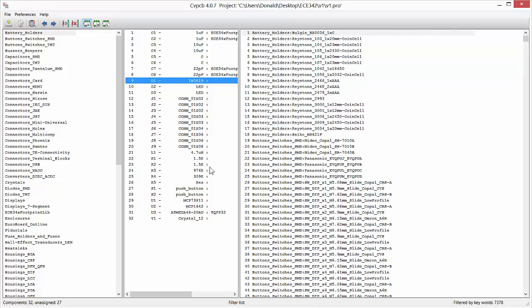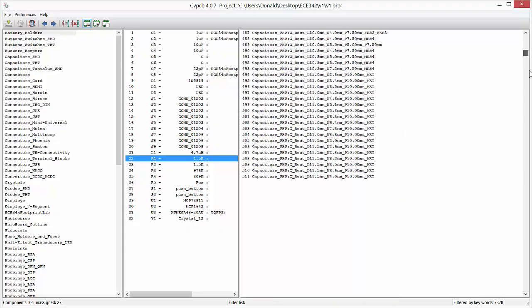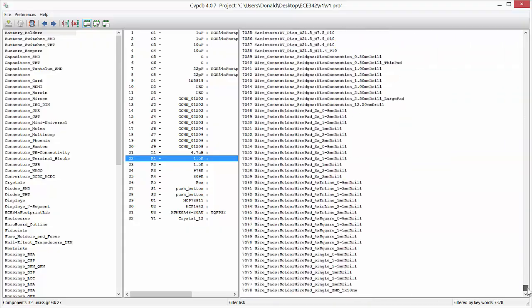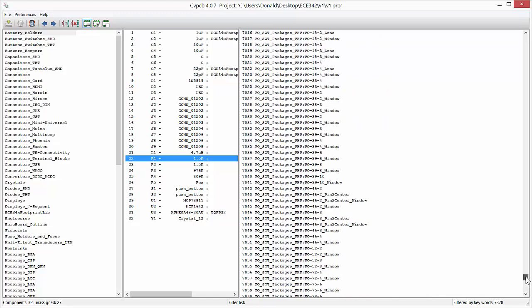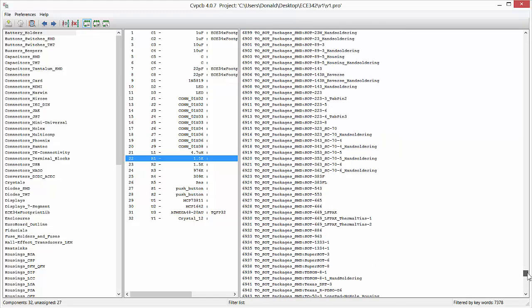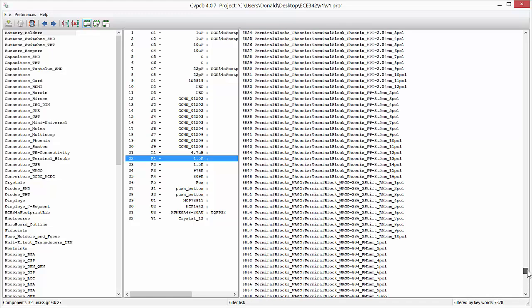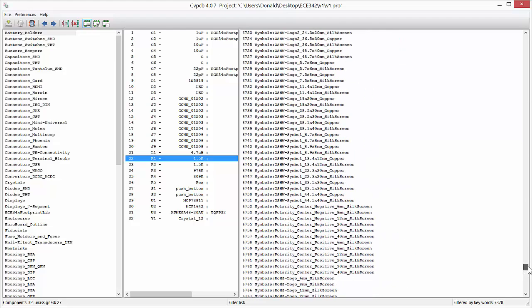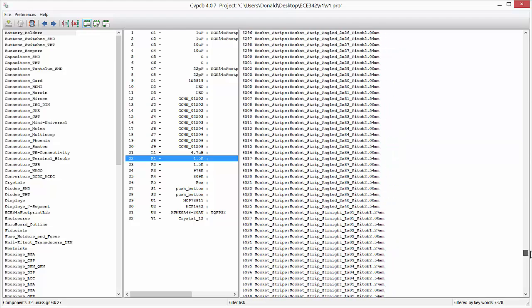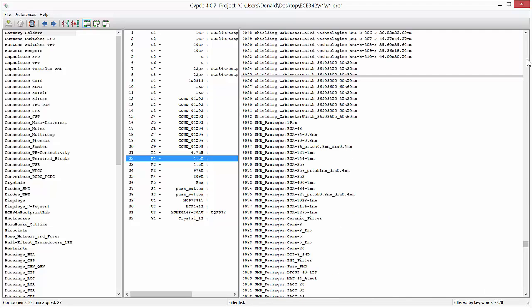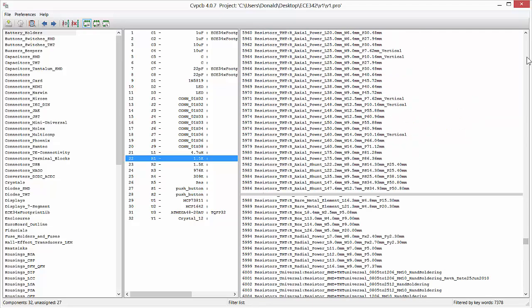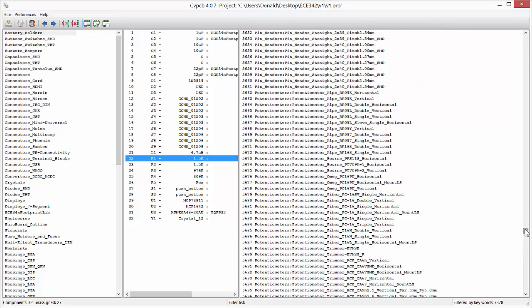See, I've got some resistors that I can probably take a good shot at, and so the resistors are also going to be 0603s. I never recommend choosing a part smaller than an 0603 if you're going to do hand assembly, unless there's a real good reason to. In fact, 0805s are much easier to use, even than 0603s. But you can hand do 0603s. It's just a little bit of work.